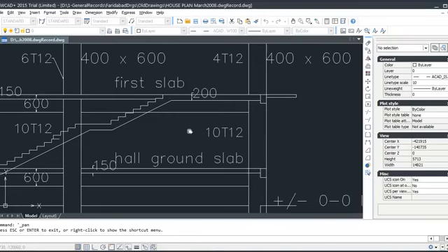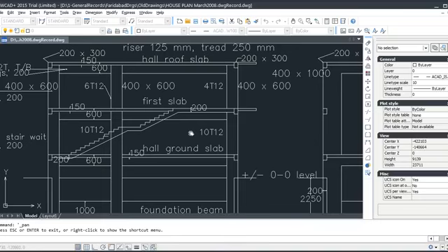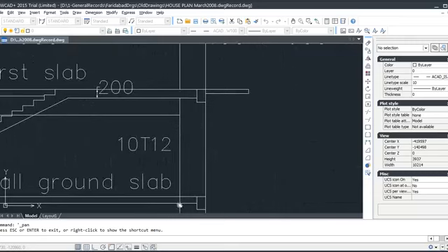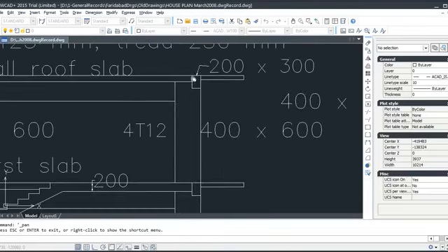Practically, beams and slabs, which you call lintel, are cast monolithic, and also a small portion here, because sometimes they cast columns up to here, and this portion is left. This portion they call the neck actually. This portion, this beam portion and this slab portion, wherever it is, are cast monolithic.